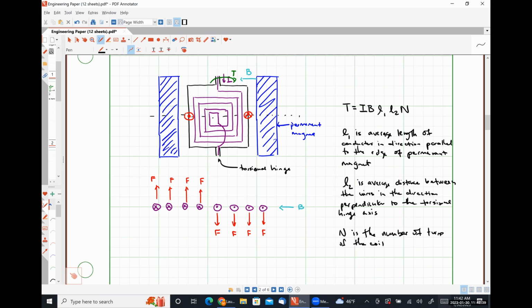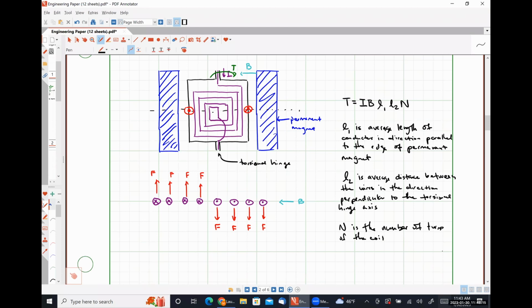So we can figure out what our induced torque is. And then knowing our plate dimensions, we can determine the amount of displacement we see of the plate and all that kind of good stuff. And we can also compare this induced torque to the restorative spring torque of our rotational springs as well. If I were to, I don't know, assign you a problem asking you to do something like that, which seems quite likely. All right, so this is a simple single axis scanning micromirror.